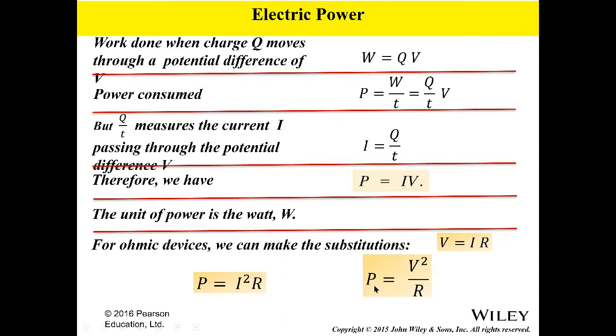If it was rated at 1500 watts in this country, you brought the same hairdryer to be used in Europe, and you plug it in to the circuit over there, then it will be drawing 4 times. It will be 6,000 watts because the resistance is the same, but the voltage increased by double, therefore it is 4 times. And what happens is your hairdryer burns out.